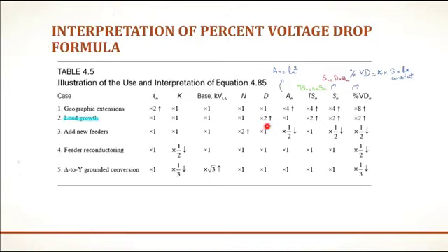When load density becomes double, there is no impact on the area served by one feeder. The reason is area is a function of length, not a function of load density. Now let's see the load served by one feeder. You can see the formula over here, that is D into area. Area is not being changed as a result of load growth. D will become double, so S will become double.